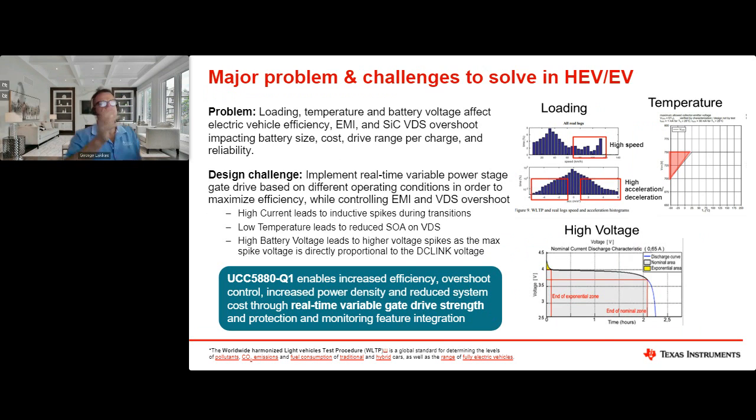So what are the major challenges that we're trying to solve here? If you're a traction inverter designer, you have to worry about many things. You have to worry about the motor current, the loading, the temperature, and the battery charge and voltage, because all these affect electric vehicle efficiency, EMI, as well as the overshoot on the silicon carbide FET. And they can impact the battery size, cost, drive range per charge, and reliability.